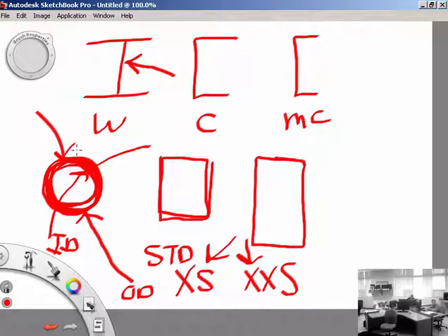Next time you're at a gas station, look at these columns that are holding up your roof system over top of your head when you're pumping your gas. They're going to be basically steel systems, but they may be massive steel pipes or massive steel tube. That's straight up what they just buy and use for steel framing. So I'm going to be concerned about OD in that scenario because I may be more interested in the overall look. It matters in different fields, so as you're doing the fabrication and worried about the prints, you need to be checking that too. Am I dealing with ID or OD? The charts will always tell you, so you've got to go to that. So a lot of things to consider when you're going through this kind of work.